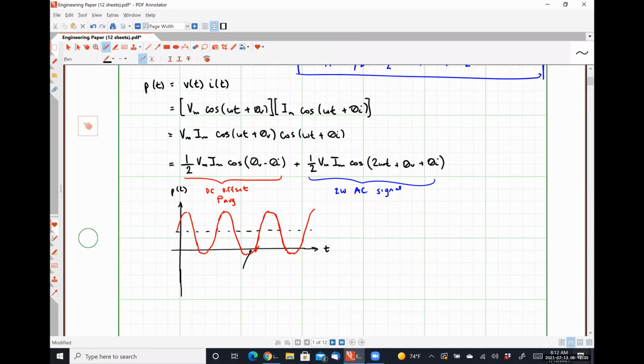So what does it mean on a graph when you go below the horizontal axis? It's negative, okay? So if this graph is representative of the power absorbed by our element, then yes, that means that over those very small intervals, our generic element here is supplying power back to our system. We will observe that that happens anytime we have capacitors and inductors in our circuit, because we know that they are temporary energy storage elements.